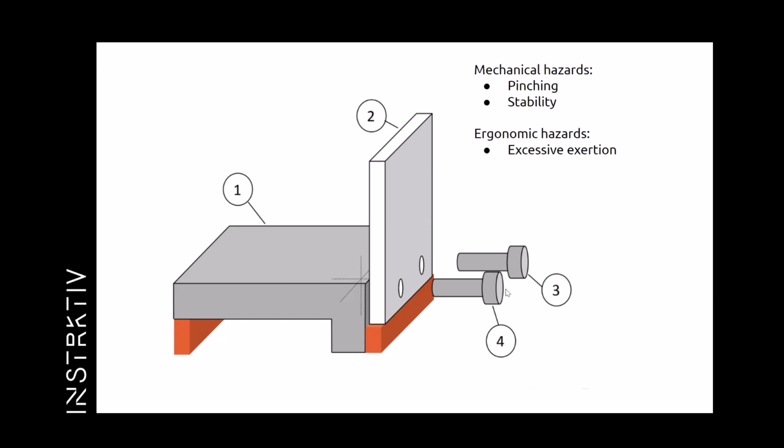When you find a risk and it's not acceptable, the first thing you can do is improve the design. If there are still risks, the second thing you can do is provide safety measures. And then at the end, when there are still residual risks, you have the opportunity to provide information with the product, such as user instructions, but also marking or warnings on the machinery itself.